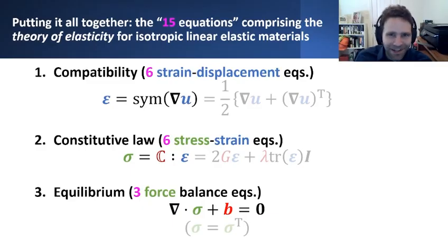In addition to that, as an aside, also an important consequence of the fact that if we were to consider imposing moment equilibrium on any small chunk of material in this particular body or domain of interest, then in order for us to maintain that condition of moment equilibrium, we also had to have this local criterion on the stress tensor being symmetric. So not only do we have this governing differential equation basically telling us the sum of forces equals zero at every small chunk of material in this domain, but also the stress tensor has to be symmetric.